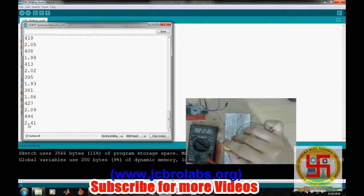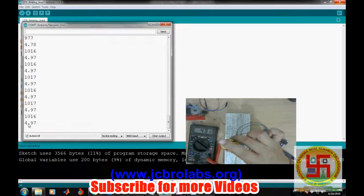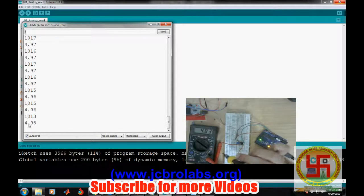So you can say now it is 2.4 volt and it is showing 2.2. The difference is less, and if we make it 5, now 4.78, no 4.99. Okay, so the maximum value it is showing is 4.78 while it should be 5 volt. So there is a gap of 0.2 volt here, and that is because of some error in the multimeter. Okay, so more or less the concept is clear, we are getting nearly the same voltage, so this conversion is doing very fine.